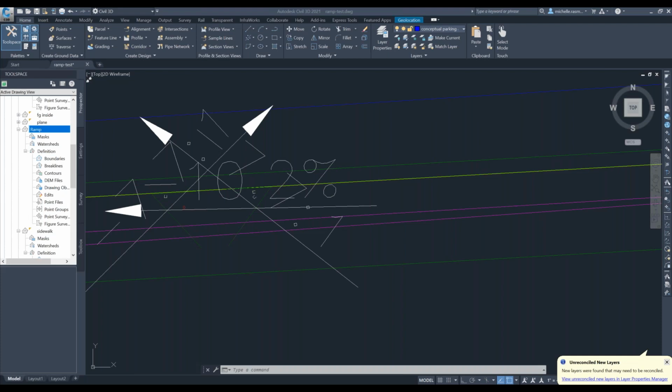One of the comments that came in from Ezra is that the 7.7 to 1 is greater than a 10 to 1. That may or may not be out of spec according to the standard. If the standard measures that slope for the wings of the ramp parallel to the sidewalk, then we are absolutely within spec, because that is how that grading object was built, parallel to the sidewalk coming out from there. So great.